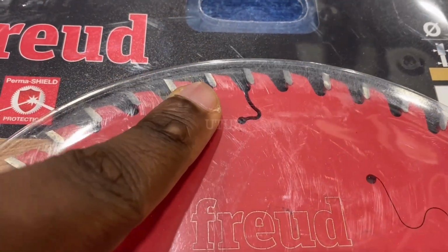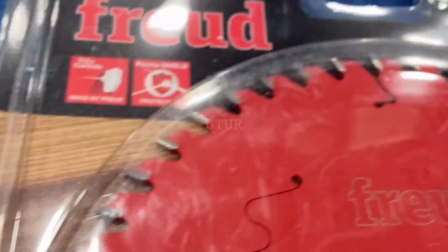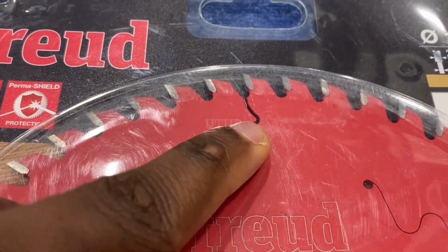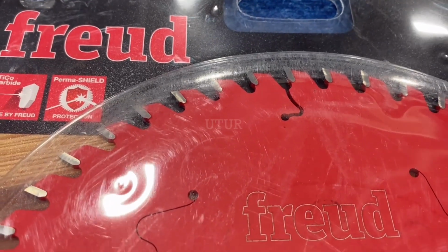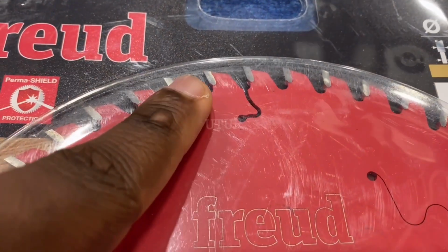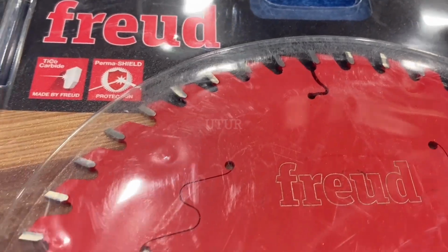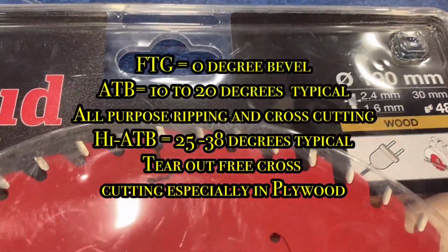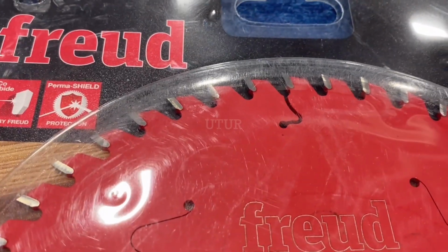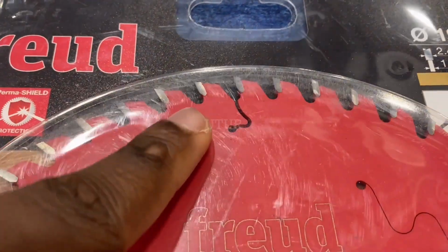Suffice to say, blades with a 0 or negative hook angle are better suited for your radial arm saws and miter saws because they prevent self-feeding or climb cutting. The blade type tooth configuration is an alternate top bevel, as the bevel tooth angle is 15 degrees. In general, an alternate top bevel tooth configuration, which falls within the range of 10 to 20 degrees typical, is an all-purpose ripping and cross-cutting blade.